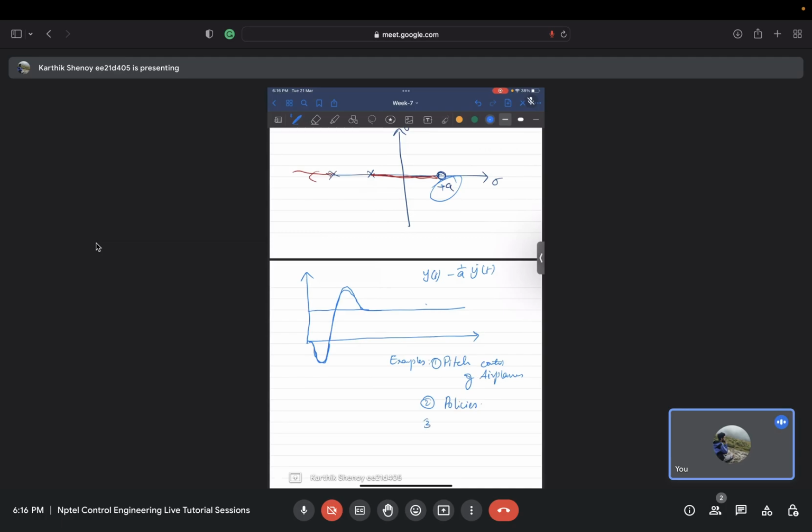And when you cycle, it's very difficult to notice. If you turn your handle while steering, when you cycle, if you want to go to the right, the cycle actually moves to the left a bit and then right. So that's the problem. You would have seen some YouTube videos where they drive the cycle in reverse, which is very difficult because of this phenomenon, because your brain can't handle it. If it turns right and it goes left, your brain will get confused, right? So there is a non-minimum phase zero in that also.